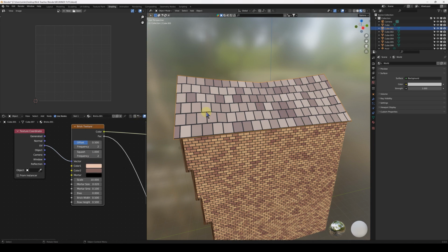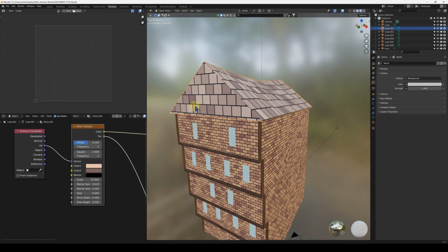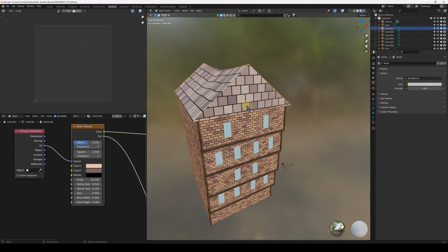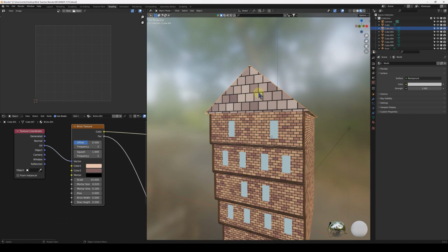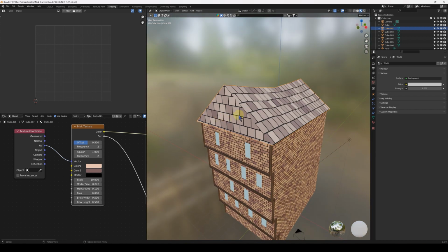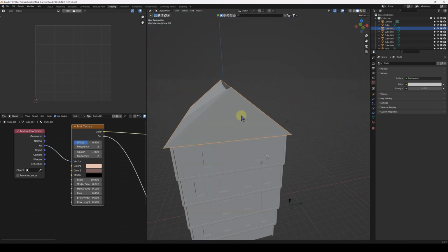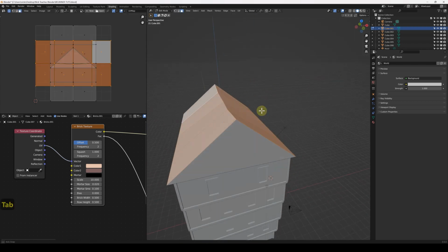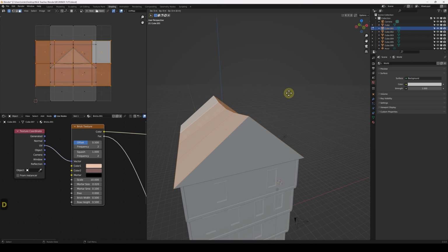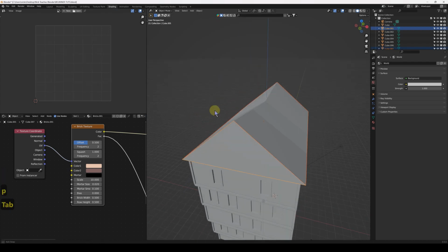Just going to lower. I don't even know if they had. Yeah, they did. We are on 6. What looks slightly unnatural is this bit at the front. It looks a bit strange. So what we can do about that is another little trick. If we've already selected these faces, press Shift D, press Enter, and then P. So we're going to duplicate that selection and then separate it.